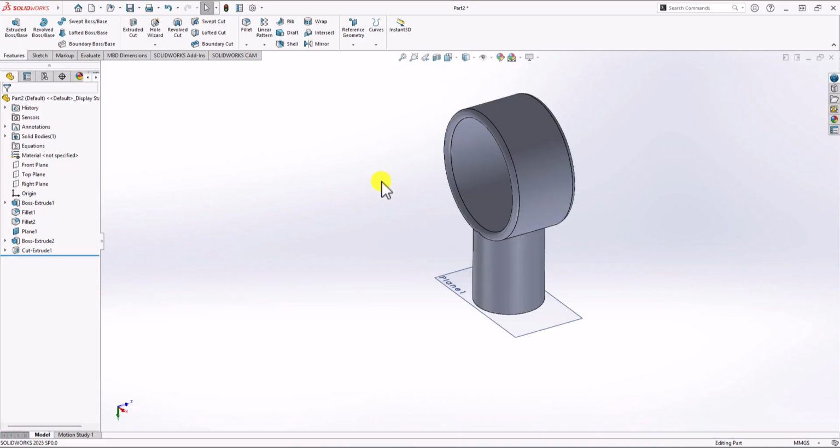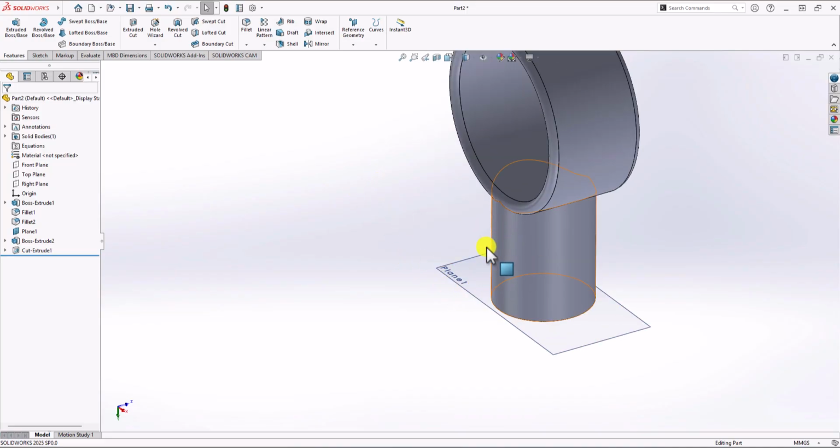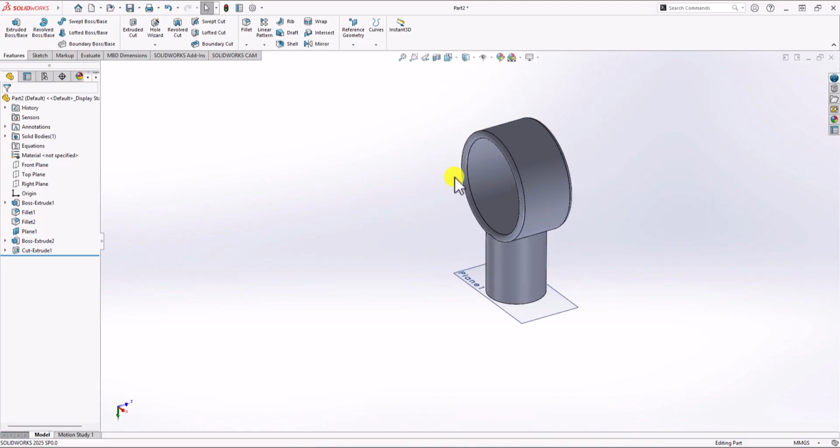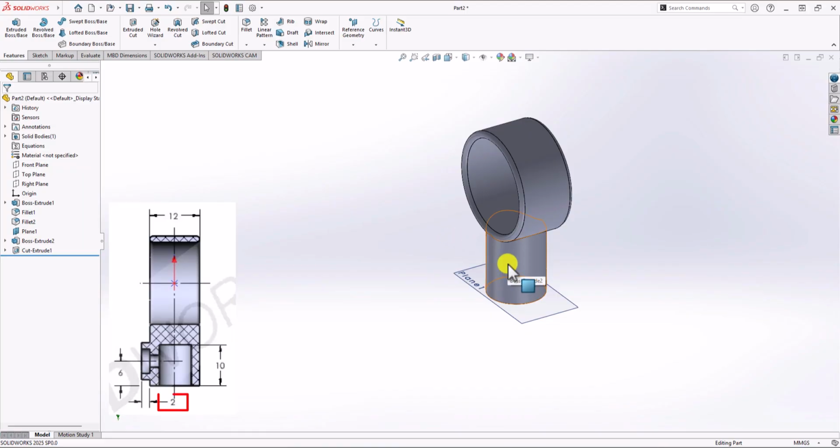Okay, so next step is to focus on a feature on a front surface of the geometry. In order to make that feature, everything is exactly the same. We need to first have a plane, then make a sketch on a plane, and then extrude it. Now the question is, what's the desired distance between the new plane and our geometry? According to section A, the distance that we need, the starting point of the feature, is 2mm away from the surface of this blue cylinder.